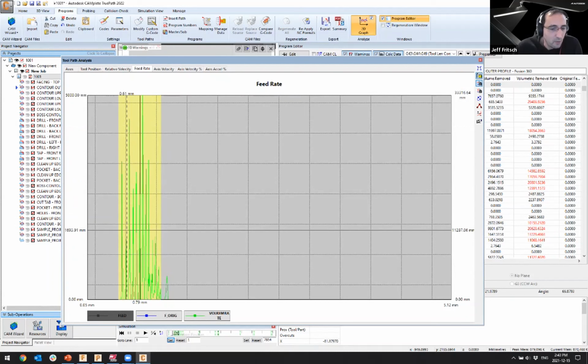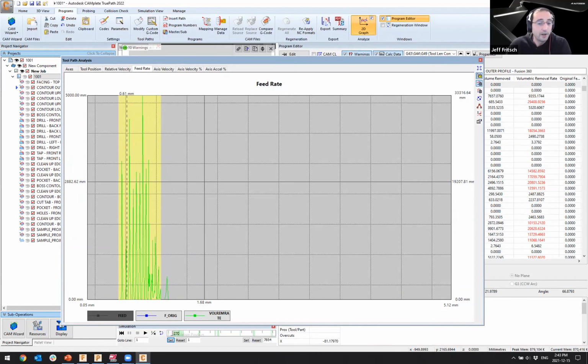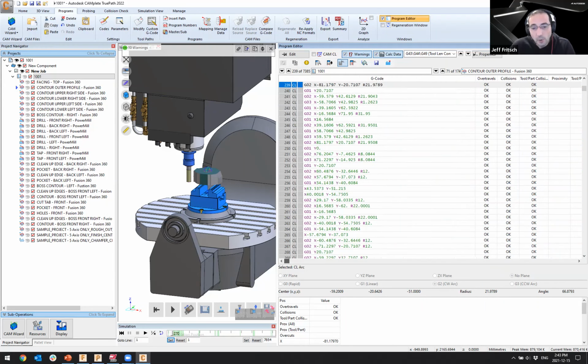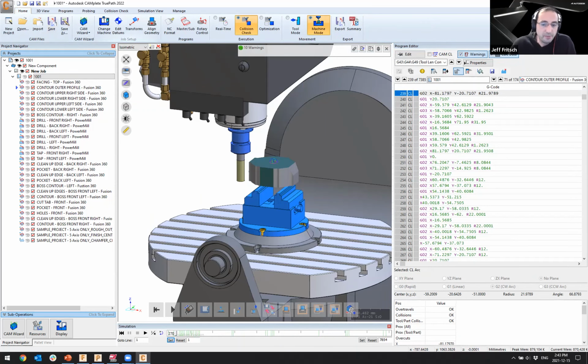We'll bring them back and check with the rest of the program. And those second passes that we can now see are already very low in terms of engagement, now being able to bring those points and double or possibly even triple the feed rates at that particular second pass, because now we know there is a lot less material and there is that opportunity to drastically increase that feed rate and remove a lot more material in a much shorter period of time. So at that point, that's really where we'll be relying on this information, more so on the optimization side.